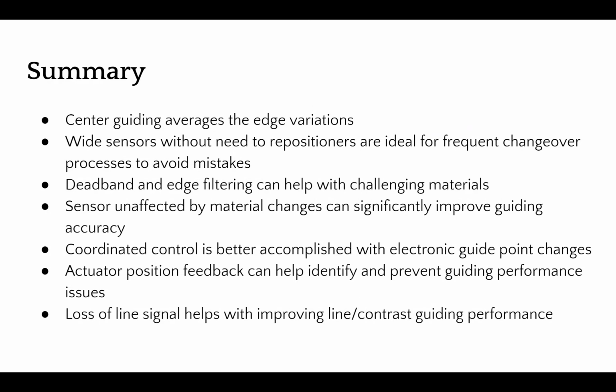Coordinated control, when you want to do multiple web lamination, it's better accomplished with electronic guide point changes. This prevents any kind of mechanical wear and tear, reduces the complexity of the system, and can provide a good performance when compared to other mechanical systems.